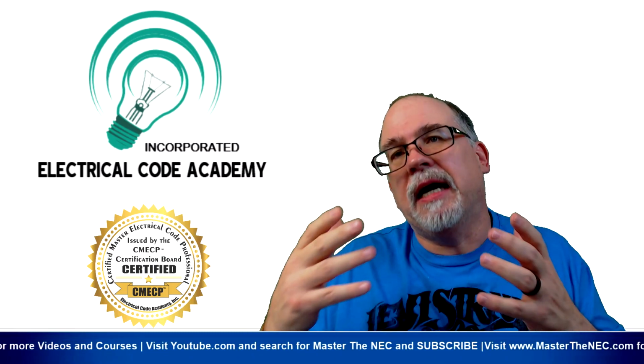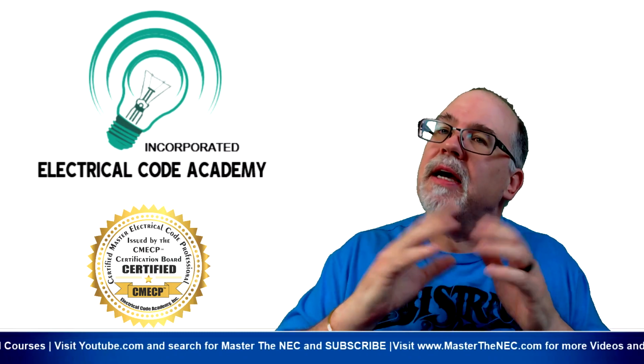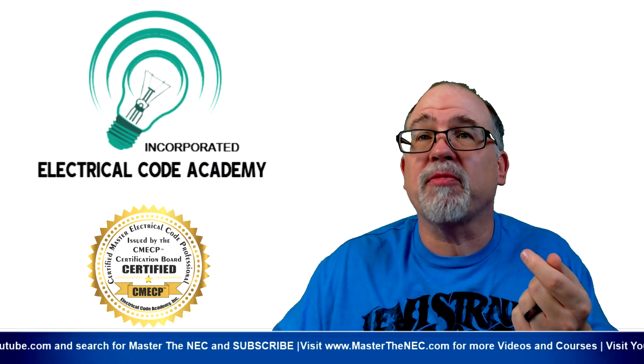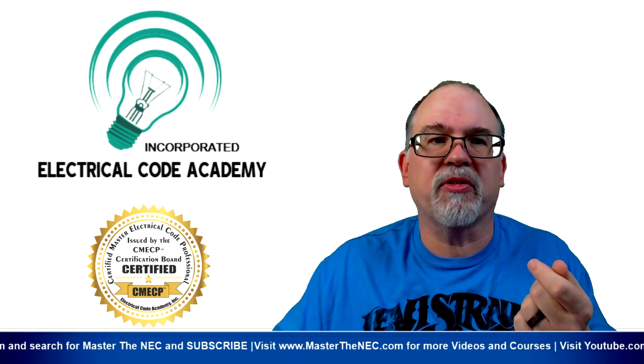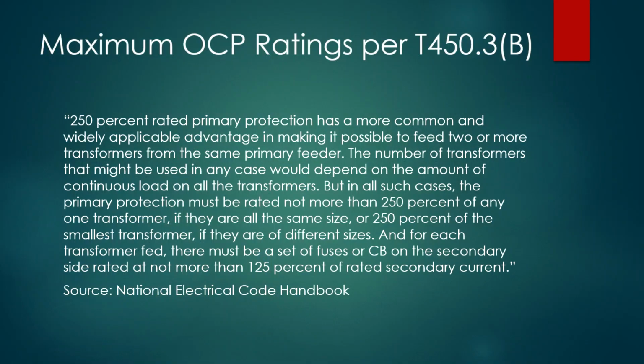That way you know that that primary is never going to exceed 250%. Okay, so if they're all the same size, you just take one of the transformers and you do it that way. But if they're different, then you simply take the smallest transformer when you're applying this 250%. Okay, and we'll finish this one out here. It says, or 250% of the smallest, if they are all different sizes.